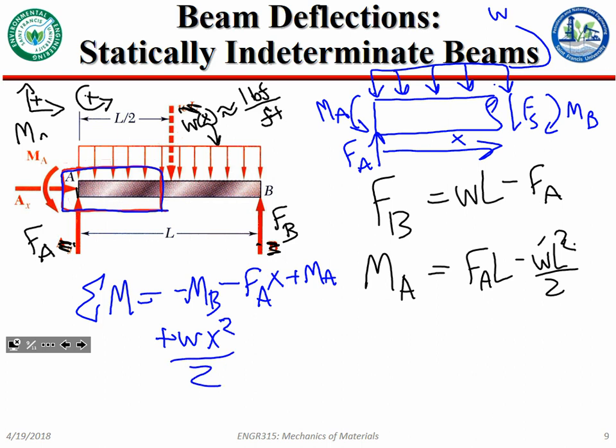That'd be the summation of moments at that section. And if I wanted to, I could substitute in everything that MA is. So I have an expression that's totally in terms of FA, the force at this support.